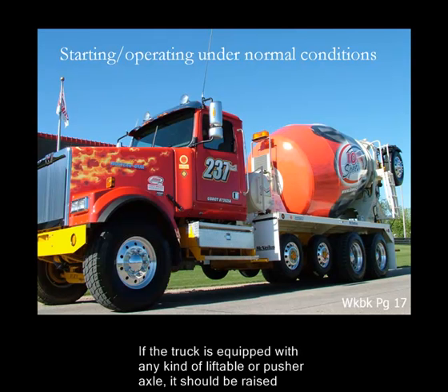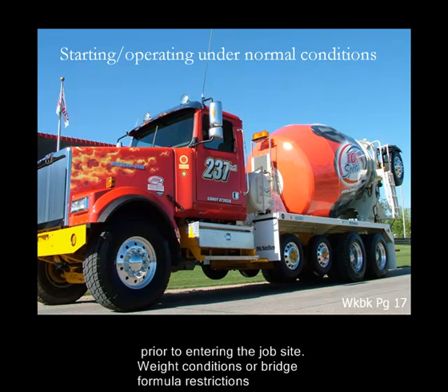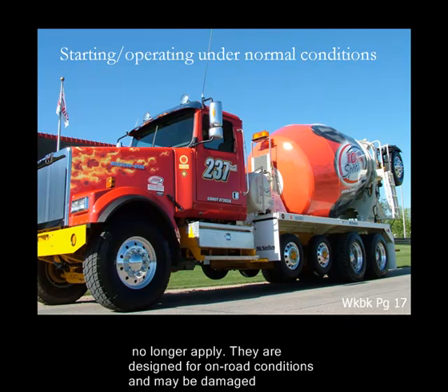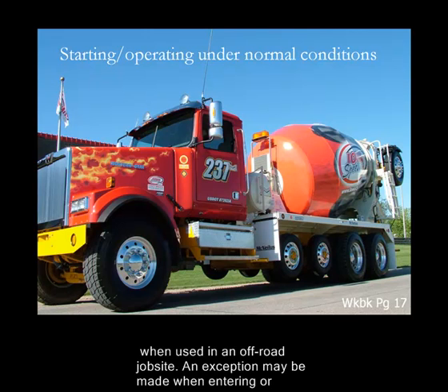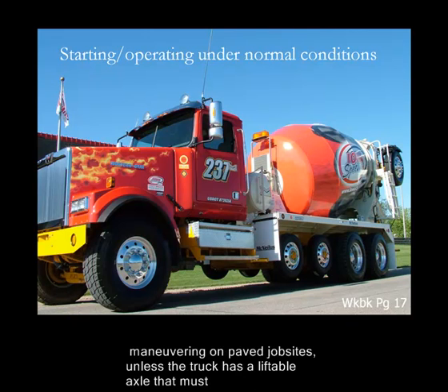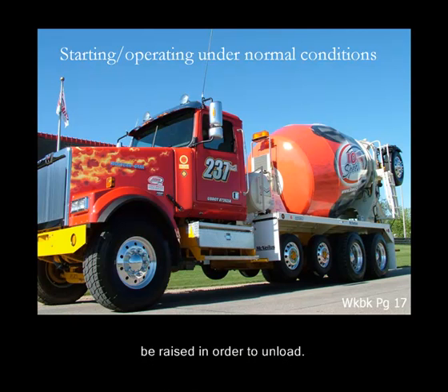If the truck is equipped with any kind of liftable or pusher axle, it should be raised prior to entering the job site. Weight conditions or bridge formula restrictions no longer apply. They are designed for on-road conditions and may be damaged when used in an off-road job site. An exception may be made when entering or maneuvering on paved job sites, unless the truck has a liftable axle that may be raised in order to unload.